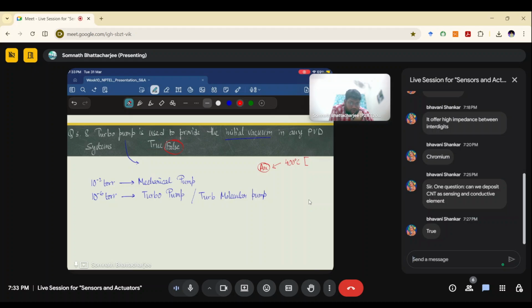The gold will suddenly melt and then it will evaporate all together, at an instant. So what we need to do is go to 100 degrees, then to 200 degrees, and it will gradually start the evaporation process, and then it will create a uniform evaporation rate. We need to get a very uniform evaporation rate.